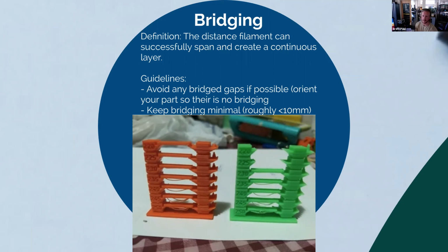Or you can not use it. You don't have to put the chamfer in, but then you run the risk of, say, breaking your part as it comes off the bed. And the chamfer only applies to parts with really large surface areas that are sticking down on the bed. If it's a small surface area, it'll pop right off, no problem.